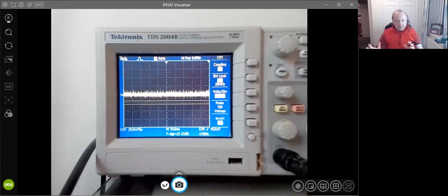If I'm doing analog and digital, I split things very carefully, and we'll talk about that next time. And I do power line filtering, planes. So it's quite a big subject, but you've got to keep it clean. Otherwise, you're going to end up with noise, like we can see here on the oscilloscope for sure.